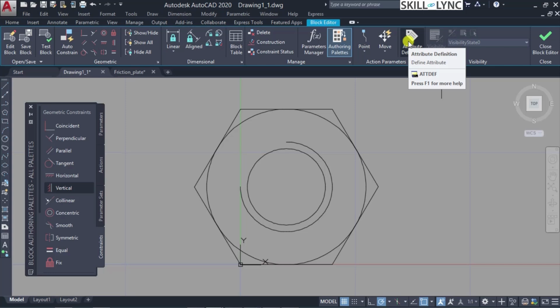These are the attributes that you are assigning to a given block, so that they can be used as information to cross-reference, for example, your bill of materials and so on. Also, these attributes are only visible for information during your editing or drawing operation, and during plotting they won't be visible, that is, they are invisible to your plotting operation. However, this information is going to be stored in the file. So we'll look into it again in detail.